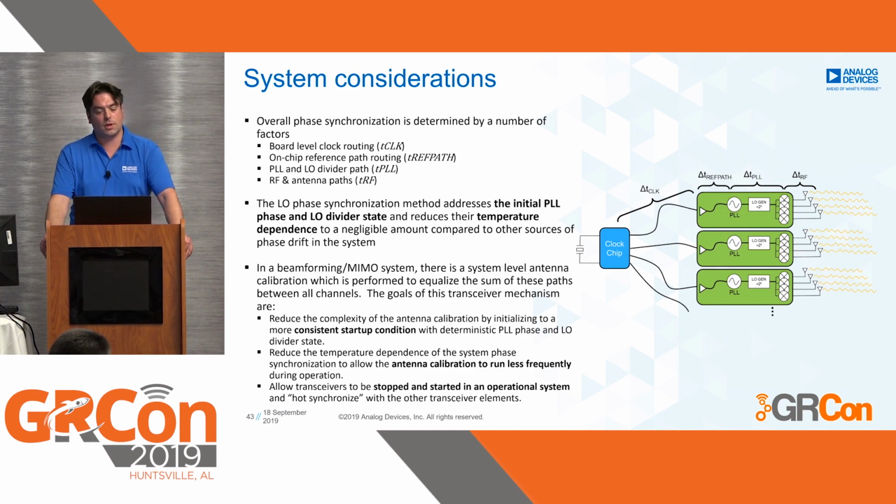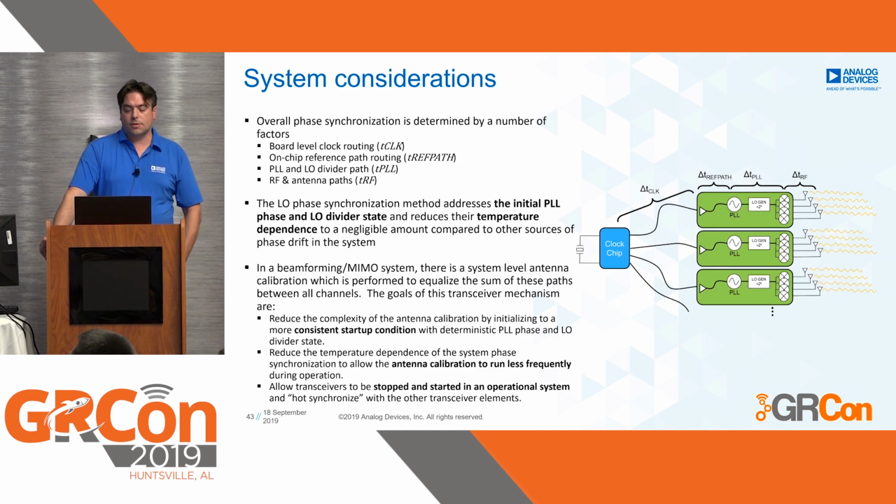The overall system considerations: the overall phase synchronization is determined by a number of factors. First of all, the board level clock routing, the on-chip reference path routing, the PLL and LO divider paths, and of course also the RF and antenna paths. The LO phase synchronization that I'm talking about here addresses only the initial PLL phase and LO divider stage. If you wouldn't do that, every time you change a frequency or do a hop, your phase would be all over the place because the internal dividers are not being reset or tracked.